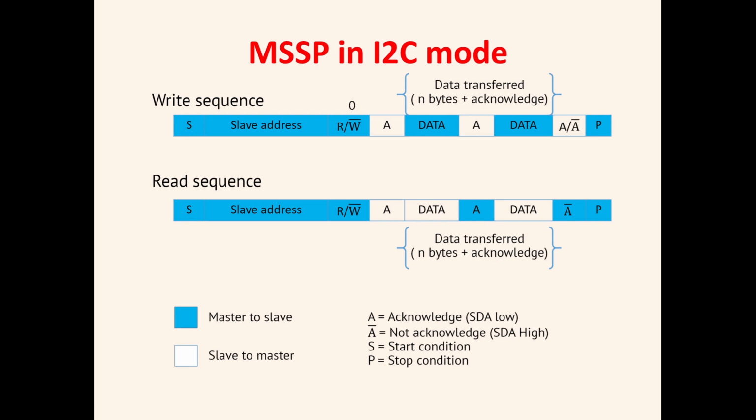After the start, you need to provide the slave address. Now, if your system has multiple slaves altogether, these slave addresses will be accepted by all the slaves in the configuration, and whichever slave address matches the slave address initiated from the master, that slave will get active.